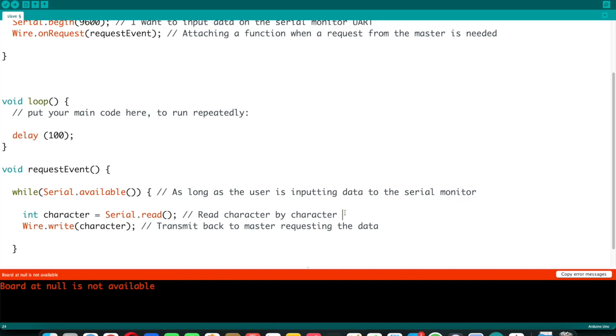And here in this exercise, we actually saw how to use the wire or the two-wire interface, which is I2C, and the UART, which is the hardware physical circuit for serial communication. However, as I told you, I2C is a software-defined protocol. UART is a hardware-implemented bus. So we've seen how to use both together. We used the serial or the UART for the serial monitor to display and to take input, and we used the two-wire interface or the I2C to receive data and send data between two Arduinos, having a common bus, which is the I2C bus.